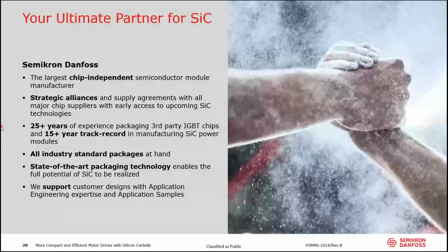We did not just start with working with silicon carbide. We've been doing it for more than 15 years. And also the sintering that I mentioned for the mini skips, we've been doing for more than 10 years. So it's almost a standard for us to sinter chips and provide the best performance there. We have all the packages that the industry uses, the standard packages at hand, and can put our topologies in there as customers desire. We have a lot of packaging technologies at hand that can provide substantial benefits compared to other packaging technologies that you find in the market. Sintering is one of these, but there's more.